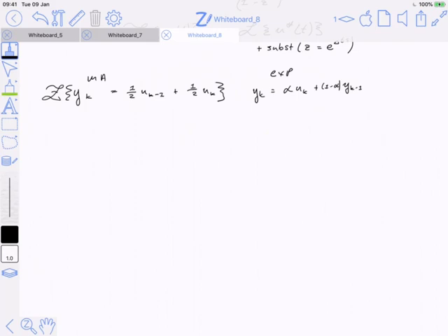Okay, so yesterday we spoke about taking the Z transform of a function, of a signal, a sampled signal. But we also did Laplace transforms of systems of differential equations. And that worked as well. So what's the equivalent in Z? Well, this is the current, right? This is 1 time step back. And this is again current. And so when we Z transform that, I'm going to end up with y of z times z to the 0, in other words, 0 time steps delayed.